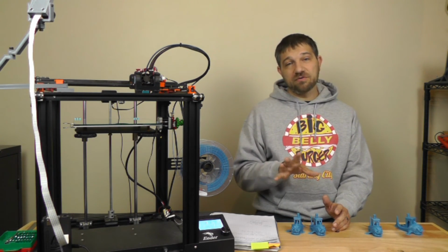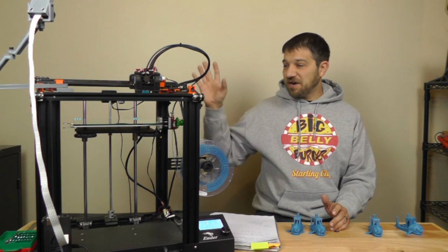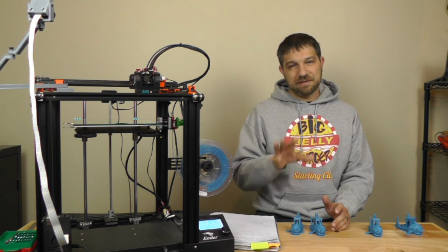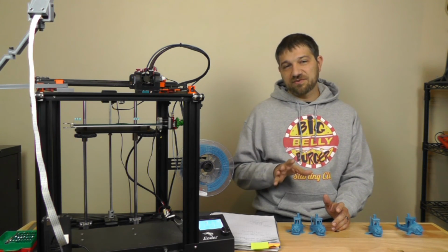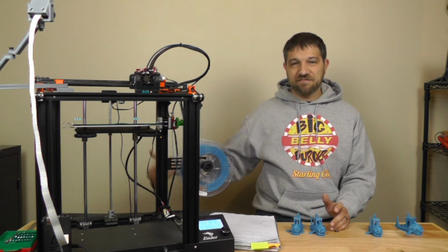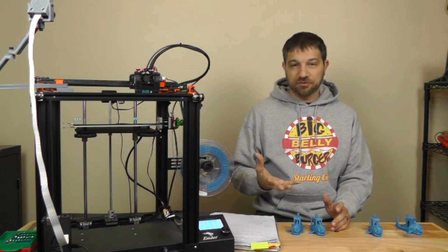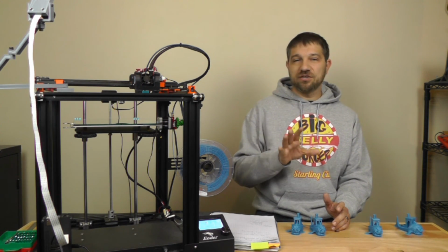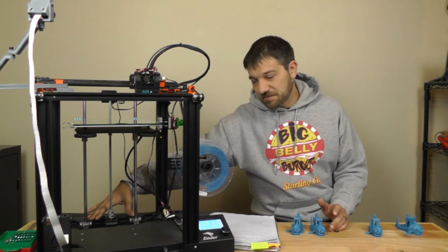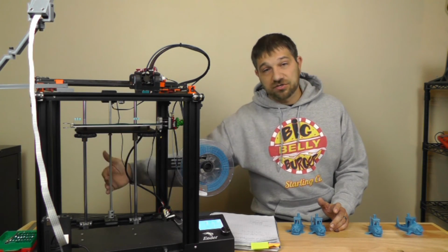Now, a couple of notes that I didn't cover before in this video. First of all, right after I installed the screw, I had some squeaking on that new screw. I'm like, is something misaligned? Is something not quite installed right? After simply taking the motors and running this up and down a few times, the squeaking went away by itself. It was just not quite lubricated correctly. If you still have some squeaking though, make sure your mountings are all aligned correctly down at the bottom of the printer so that it's not having to work any harder to turn that screw.